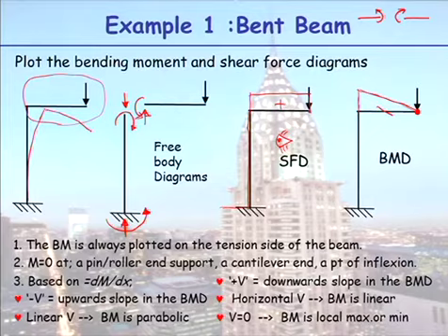So this is what I would call an inner corner. I have tension on the outside, and therefore I must have tension on the outside of the vertical face. So going around the corner, this value of bending must equal that value of bending. If you open this up and flatten it out, it's currently an L shape. If you lift up that horizontal leg and draw it straight, you'll see that these two members here should join up.